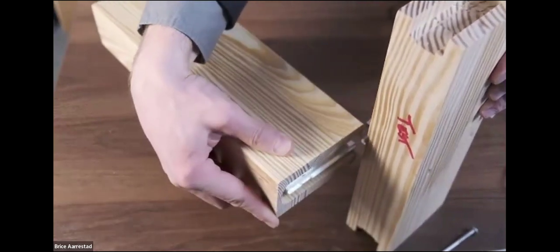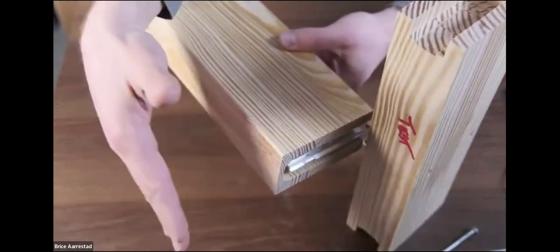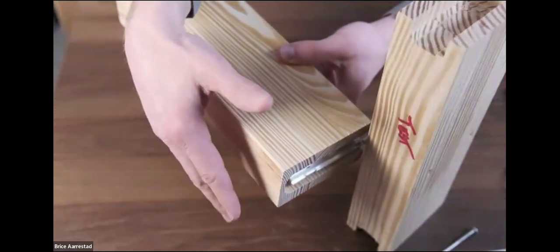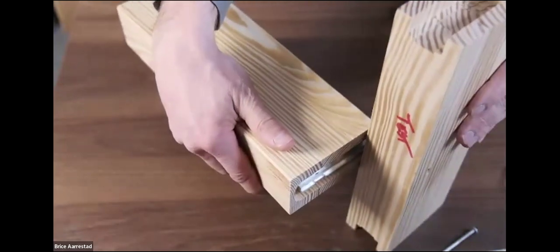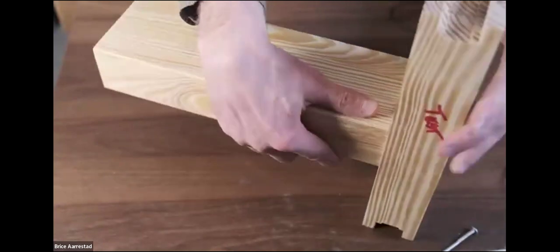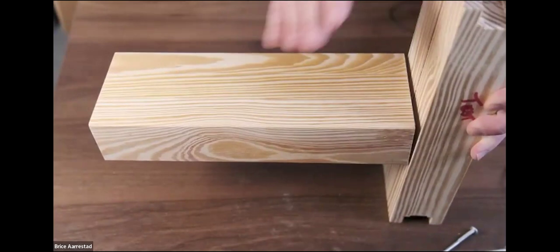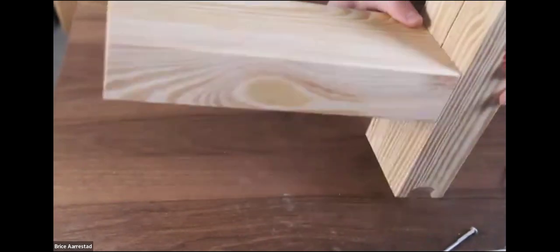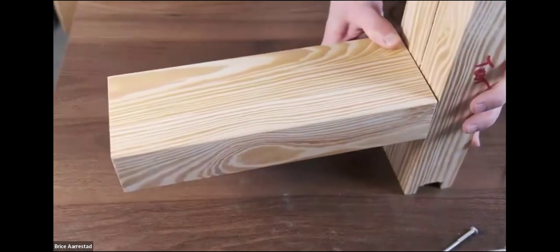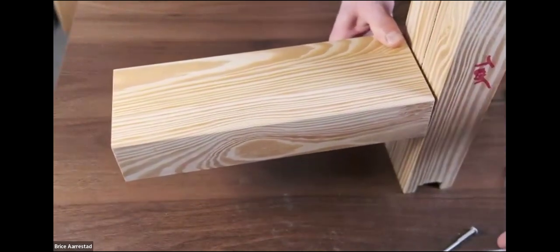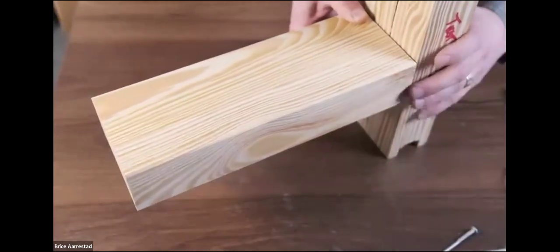So needing a little bit of clearance between the back member here, and if you have structure, if you have a column, if you have a wind girt, being able to fit that member between there. One of the things that is also unique is the ability to have different size mullions and transoms. So these ones are about 4 inches. Typically the mullions would be thicker than that.